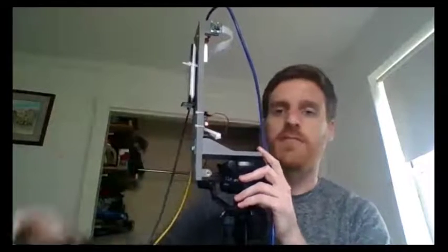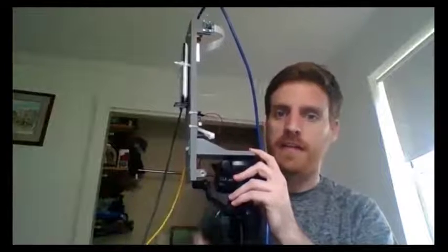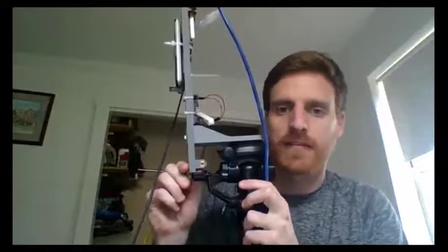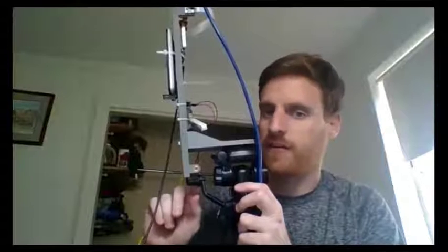Here's my LiDAR setup for the spring 2018 semester. This LiDAR relies on the geometry of the setup between the laser and the camera in order to get range measurements. There's a two-piece 3D printed mount that's easily attachable to a traditional camera mount. Located here at the bottom of the mount is a red line laser. This laser transmits a continuous series of red laser beams and acts as a transmitter or radiation source for the LiDAR. The red laser then propagates through space until it interacts with an object.